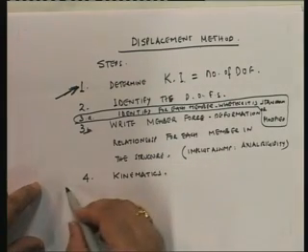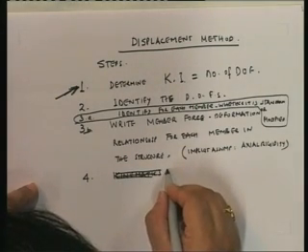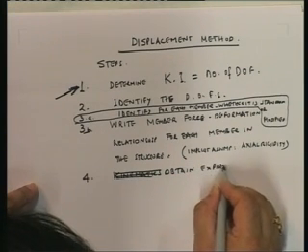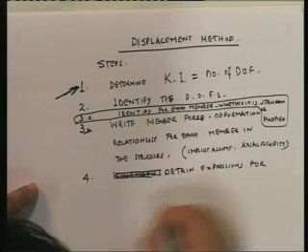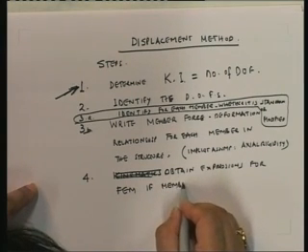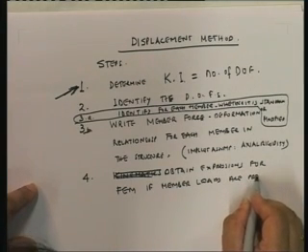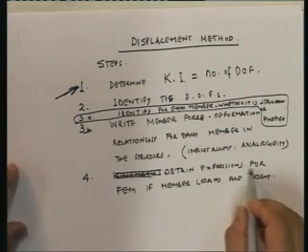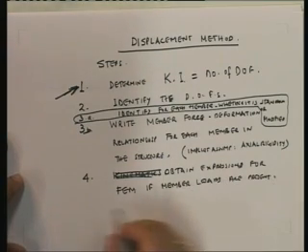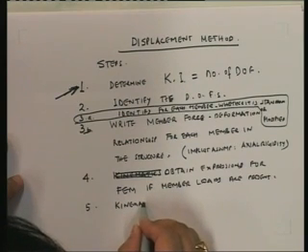Okay. The fourth step, before that, the fourth step should be obtain expressions for fixed end moments if member loads are present. Okay, so if you have member loads, then you need to do this. If the loads are at joints, then you don't need to do this. Next is kinematics.